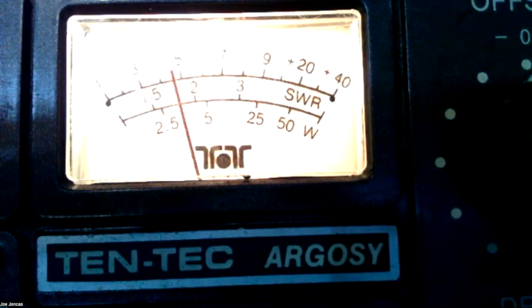The point I'm trying to make here is, if you go from a 100-watt barefoot transmitter down to a QRP transmitter, which is 5 watts, that is how much you will lose: 4.3 S units. You will go from an extremely strong signal at S9, and Scott will confirm this, he would be perfectly happy to get an S5 signal. And that's because we lowered the watts of the transmitter significantly.